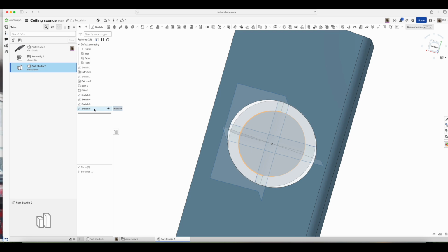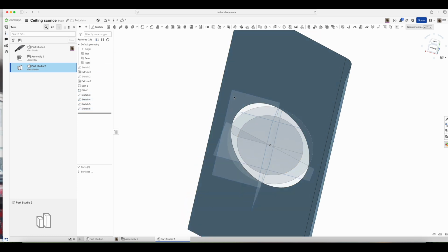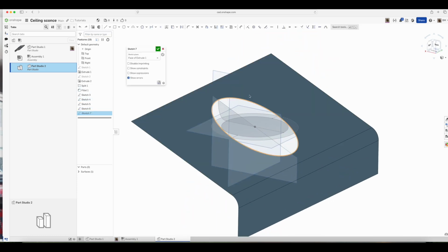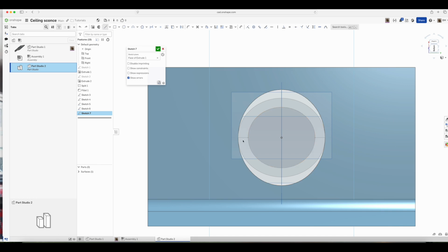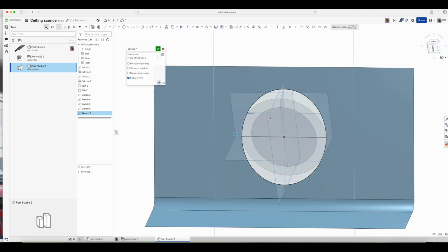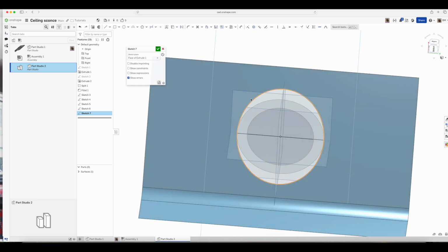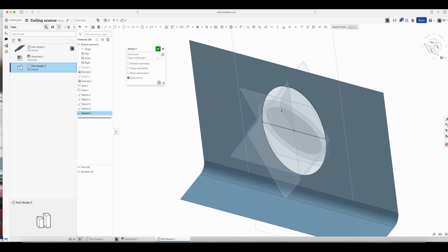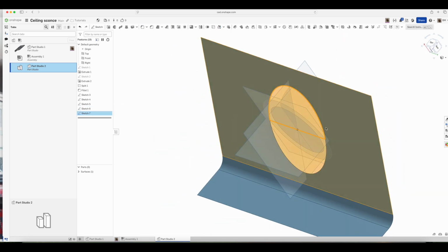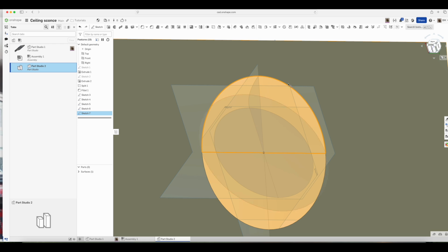And we need one more sketch here to pull this all together. And all it is, is a sketch on this face. We'll go normal to it. It's a line bisecting that, and then it is this curve projected onto this sketch plane, and then I'll use M to trim the bottom half. So we end up with this kind of semi-ellipse, half an ellipse there.